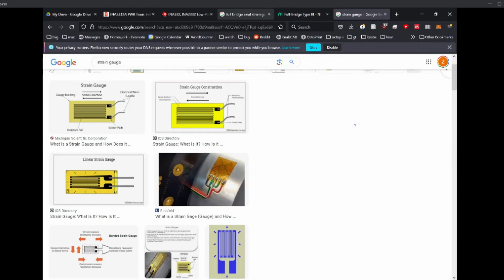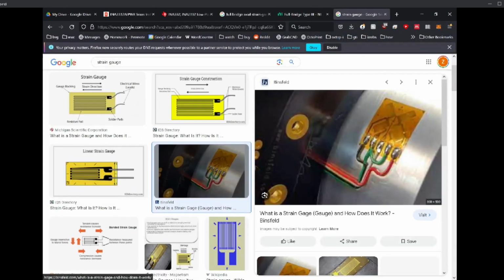So this is one way to do it. You apply your strain gauges, and then you just solder wires directly to all the contact pads. And I think these guys also made the bridge on the thing, so they're just sending back 4 wires. Send back those 4 wires of the Wheatstone bridge and you deal with it later. But with this, you need to actually CA glue down all your wires, and you need to make sure that they're in the final position.